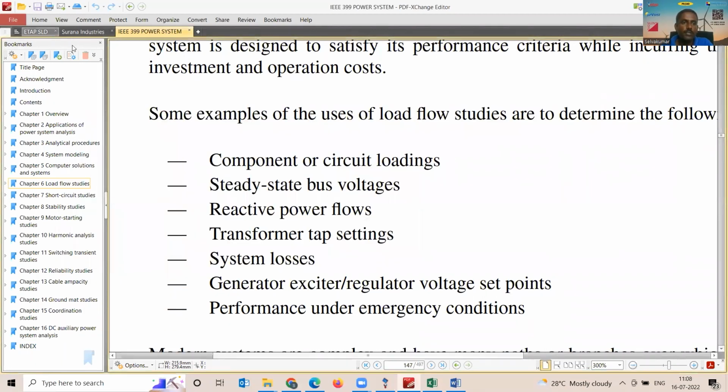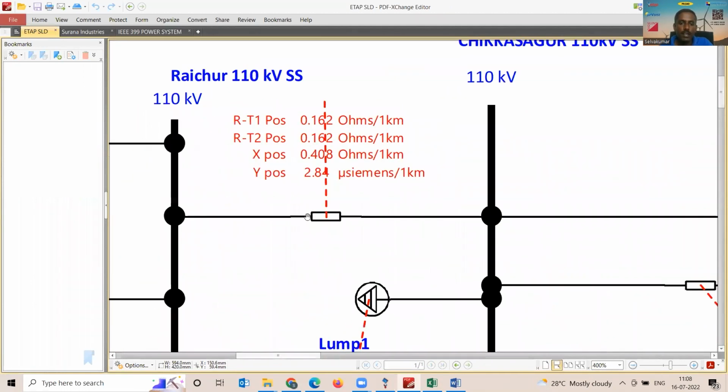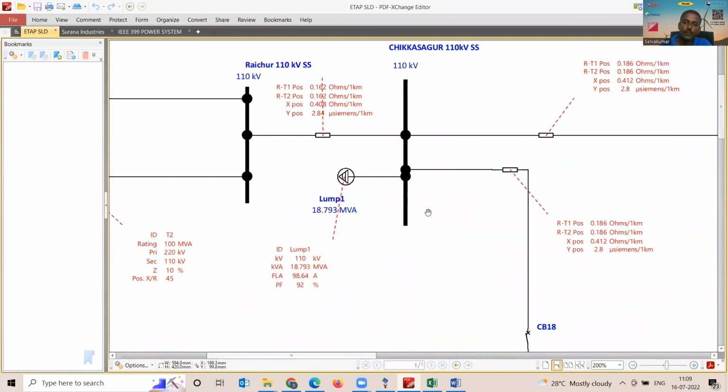When we have something like this, what's the available transfer capacity between this 110 kV substation and this 110 kV substation, over a length of about 12 kilometers? It is an essential outcome from a load flow analysis, which gives an idea in the future if some other industry asks for connectivity at this place, up to what extent this utility can extend, right?